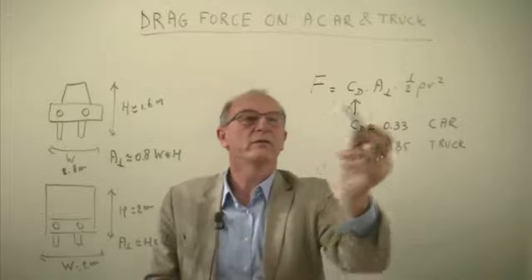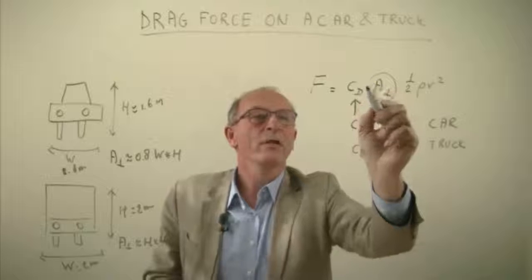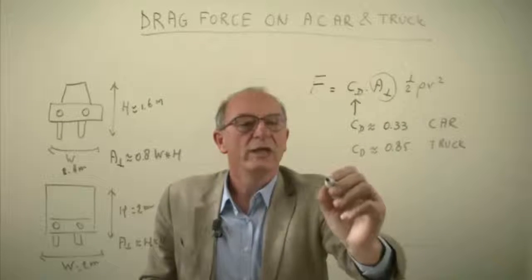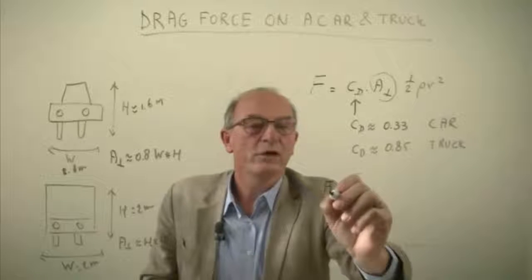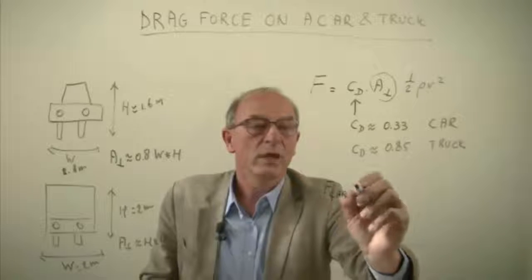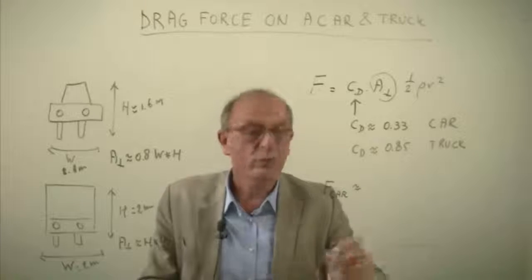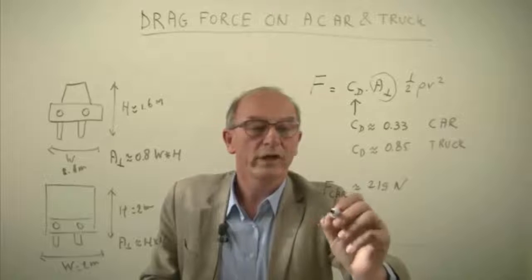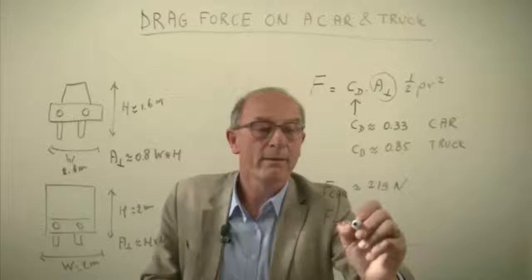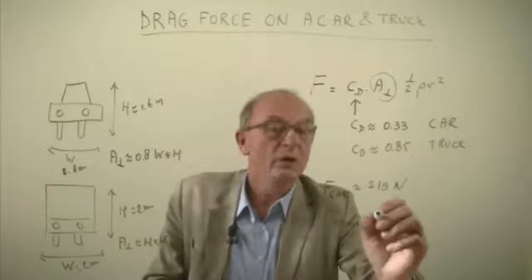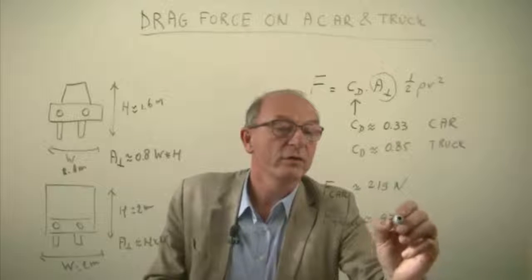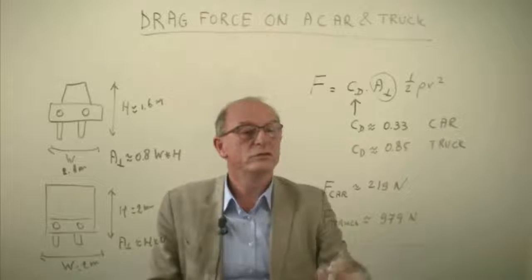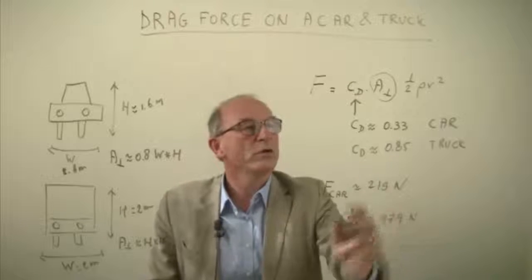First you have to calculate the surface area. Subsequently you put in the speed, which is similar in both cases. And then you can calculate the force acting on the car. According to my calculations, it is about 290 newtons. And if you compare that with the truck, this is about 979 newtons. So you see there's nearly a factor 4 between these two.